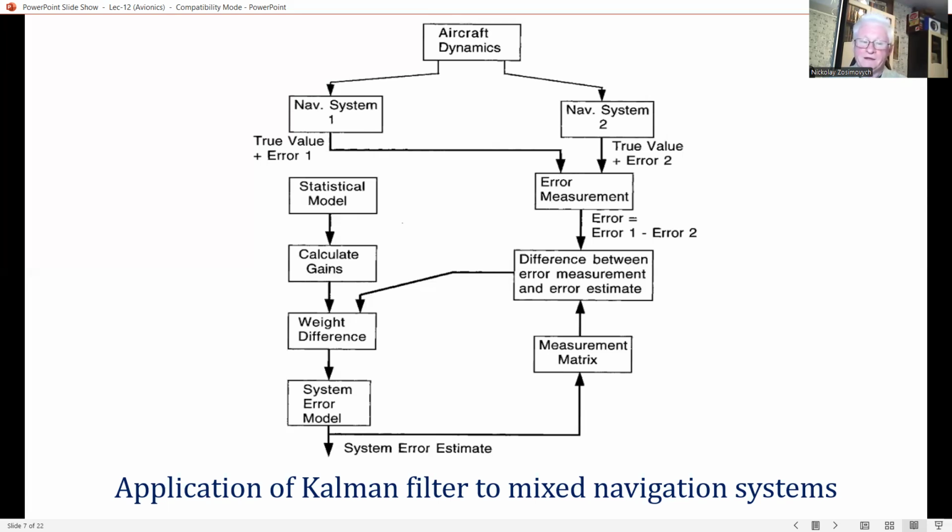can be used to improve the estimate of the other error quantities in the system. For example, the Kalman filtering technique generates an improvement in the INS velocity accuracy by virtue of the strong correlation between position error or measured quantity and velocity error, which is essentially the direct integral of the position error.